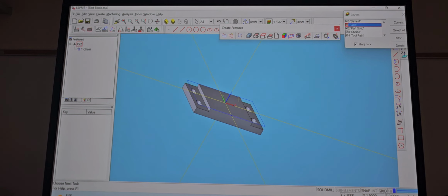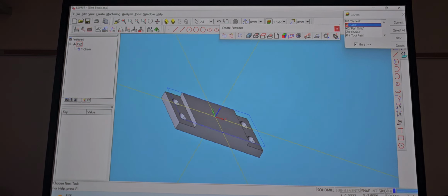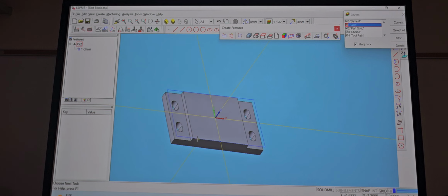Now pay attention up here real quick, guys. I know some of you guys had that issue of, you see how the arrow's facing left down here? Y'all were saying, hey, can I rotate it, or can I put another spot to where that starts at, right? On this feature, depending on if you want to do conventional or climb milling, that's probably the only issue that you would have, because we're just facing.